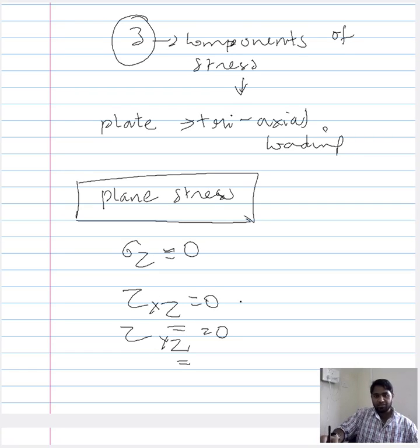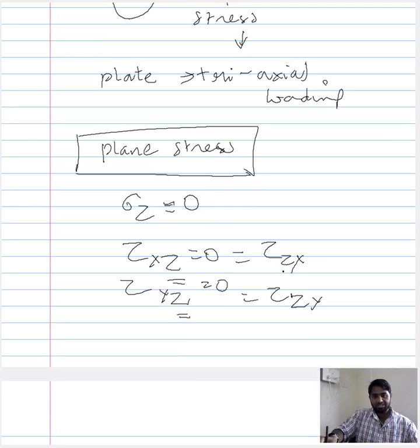And since you can write zy as something based on the z plane as well, we were able to get rid of rather 5 components, and express the stress condition based on 3 components. So the plane stress condition means the stress along one of the directions is absent. That is the simplest way of describing the plane stress condition.